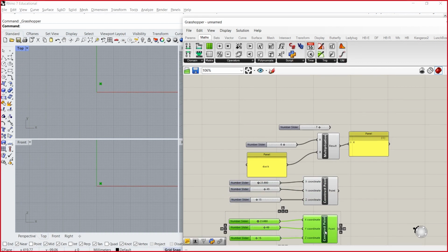I want you to select the point, Control C, Control V. Just copy it underneath. Drag it down. Yeah, so when you click on a node, it turns green. When it turns green, you can move it. Yeah. So how many points do you have now in Grasshopper? 2 points. Well, we only see 1.